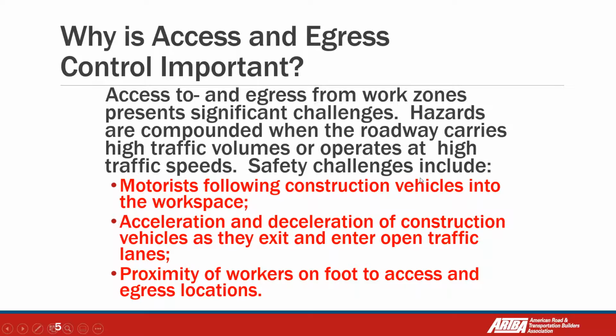Hazards are compounded when the roadway carries high traffic volumes or operates at high traffic speeds. So you are in a high volume or high speed area, and you need to arrive inside the work zone. Maybe, for example, a distracted motorist is following you, so you have a motorist intrusion there. Maybe you need to use the brakes suddenly to arrive to the work zone, and maybe a distracted driver behind you is not going to react on time, and you are going to have some problems there.